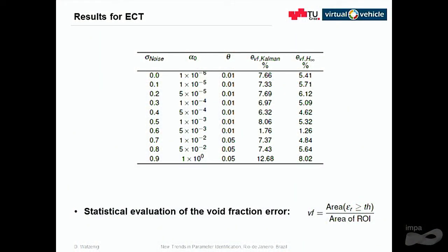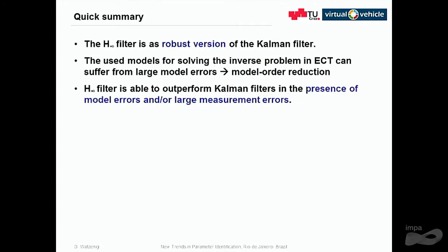And just for ECT, one table where we compare the so-called void fraction. That means the fraction of oil in the otherwise uniform background material, oil and water. And what you can see here for the specific example, the H-infinity filter is much better than the Kalman filter for this specific ECT application, and for this parameter conditioned on the measurement data. So it's worth trying the H-infinity filter in that case.